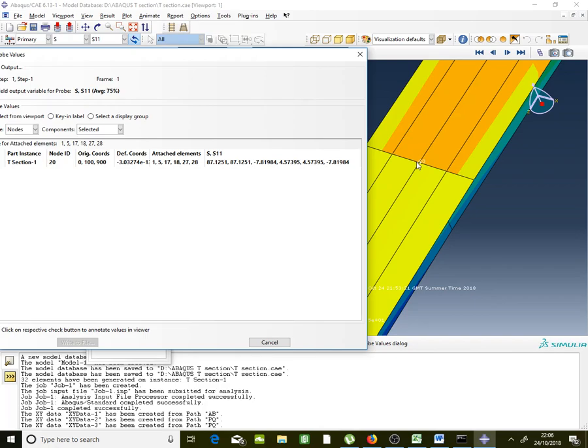Now, we are mainly interested in the value of the bending stress S11 along the joint AB with respect to the stresses in the web, because it's the maximum. So whenever you get the maximum value of the stress, that is the one we are looking for. Whenever you have any value with the maximum stress, it is the stress in the web that we care about.